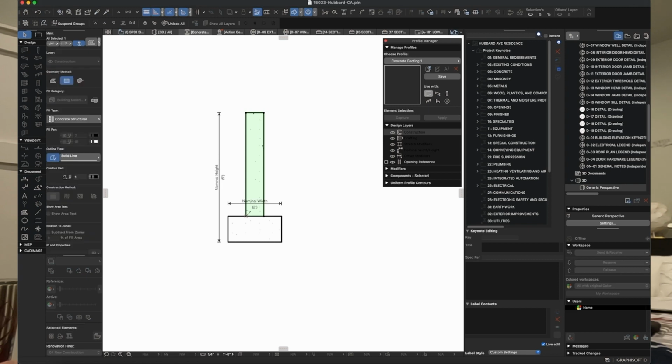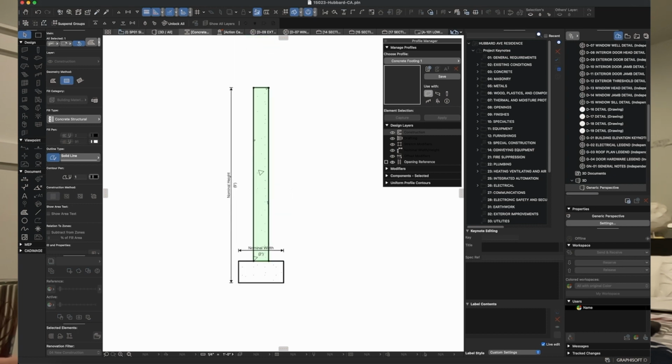Now, in a colder climate, a lot of times you'll have basements, so I would actually want to make this another 4 feet taller at 8 feet. Now, the reason why I want to do that is, a typical basement is going to be 8 feet. Sometimes people pay extra, get the 9-foot basements, sometimes 10-foot basements, but 8 foot's the most common.